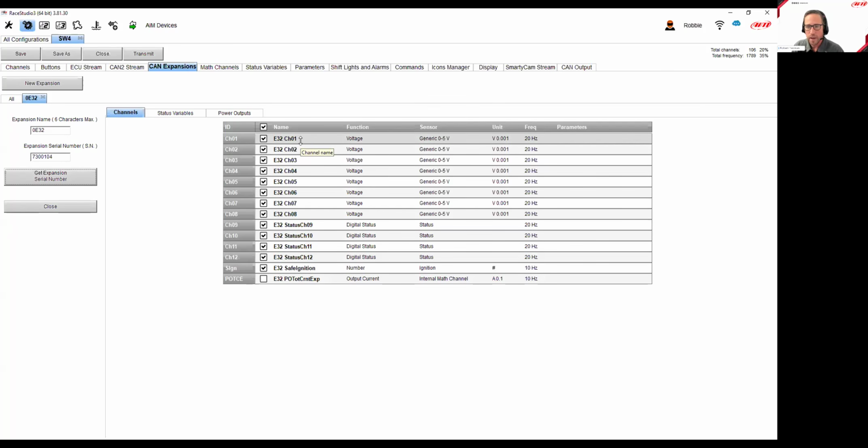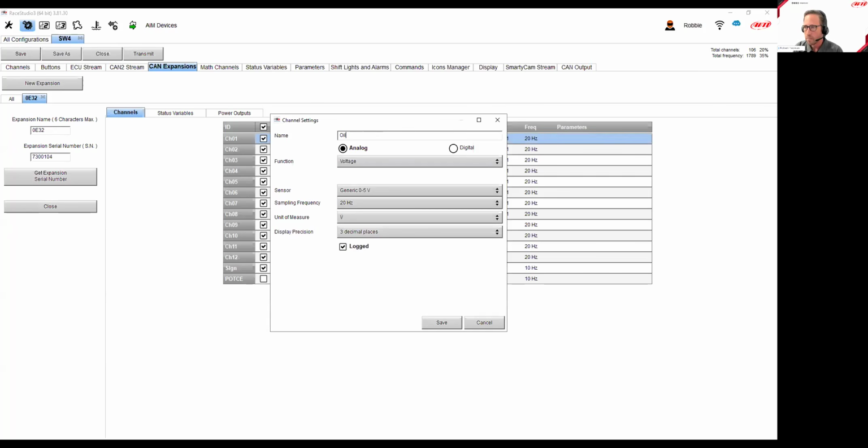If I were going to be adding oil pressure, the SW4 doesn't have any analog channels on board, so you were always going to add an ACC3, especially for the non-common ECU supplied sensors, brake pressure, oil pressure, that are operated sometimes with just switches. They either have pressure or you don't have pressure. The EPM enhances the SW4 in a way that we now have 8 analog channels, so I can use my oil pressure and just keep the number of expansions to a minimum.